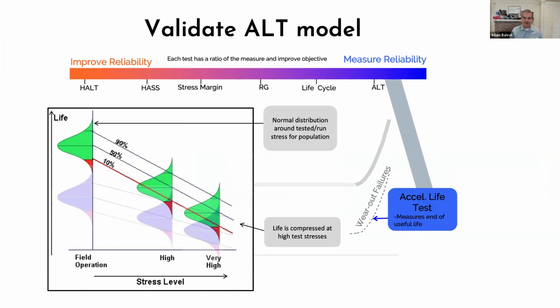The way the paint looks great doesn't have anything to do with how you put the paint down. It has to do with all the preparation. Are you going through the wall looking for where there's bumps? Are there cracks to fix? Are there parts that need to be taken out and replaced? It's going to be all about the preparation with regard to if the final product looks good. It's not going to be only how you take the brush and put the paint down.